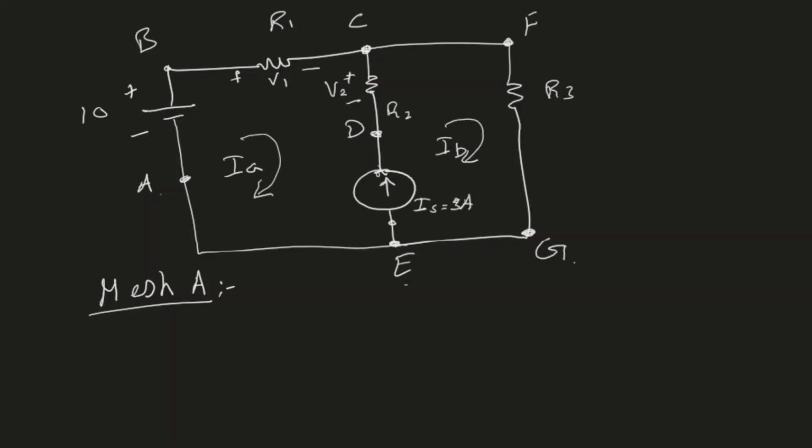So an alternative would be to go from C to F. There is no voltage drop. They are the same point. And then from F to G. So you see the voltage drop from F to G would be the same as C to E, right? It would be the same. You can think of it as the points C and F being, let's say, the second floor of a building.